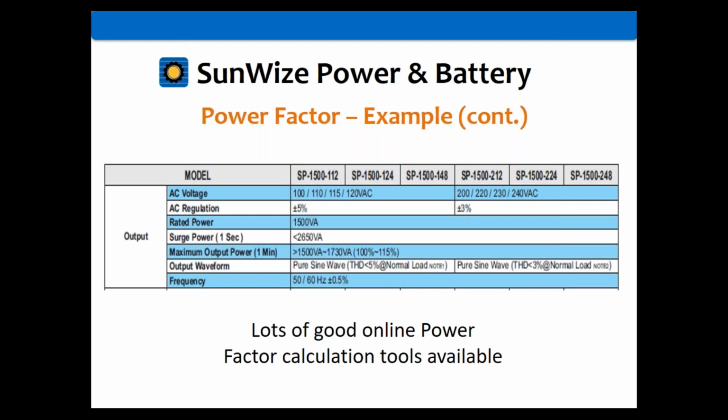Let's see, the load was only supposed to be at 250 watts. We put a 200 or 250 watt inverter on there, but it wasn't working because with the power factor, it really needed something that was 300 volt amps. And my 250 volt amp inverter wasn't going to support a load of 300 volt amps. So I had that problem once before.